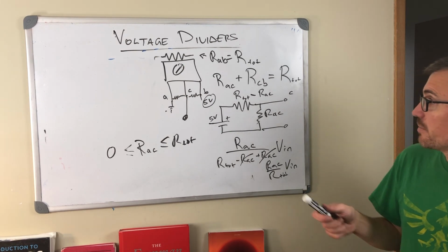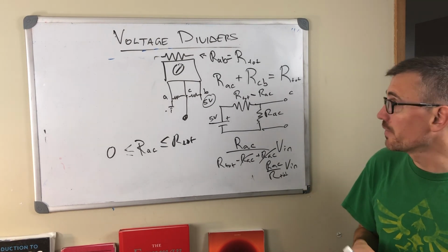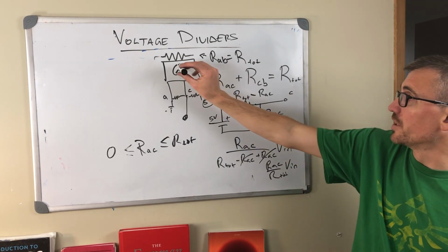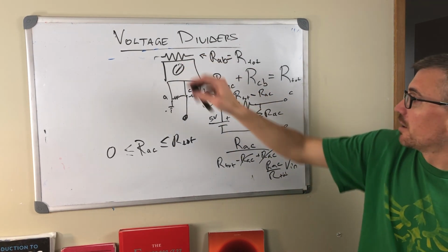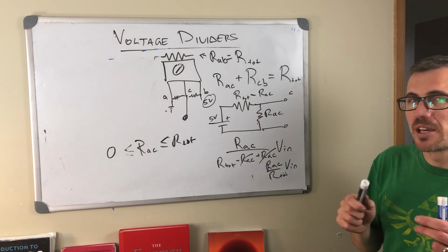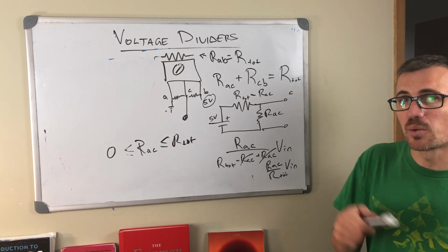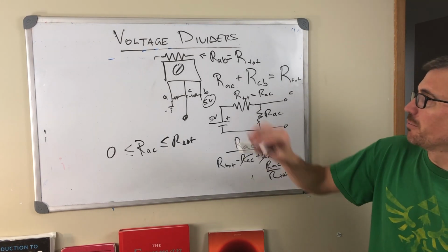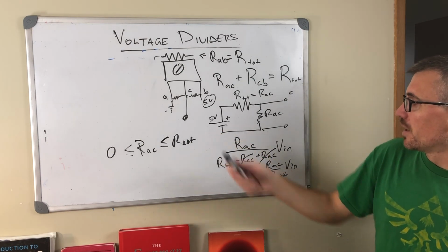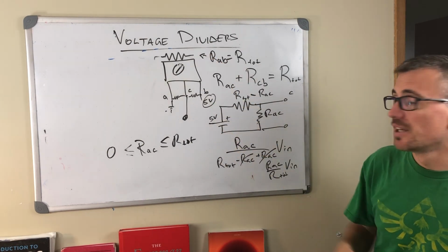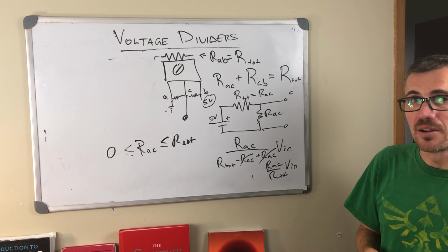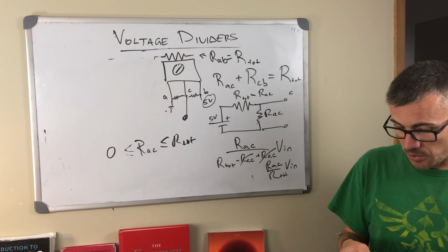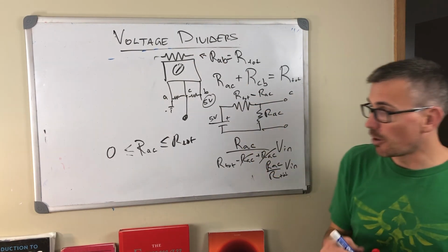So this is going to have the same loading error as we had in previous circuits, but it will get a continuous voltage when not plugged into anything between 0 and 5 volts. And if I want to make this a great voltage source, we just have to wait a couple weeks, and we'll hook it into what's called a follower op amp. And then we'll just get a beautiful 0 to 5 volt continuous supply without any loading error. All right, but that's getting a bit ahead of the game. For this lecture, I just want you to pick up the basic topology of the voltage divider.